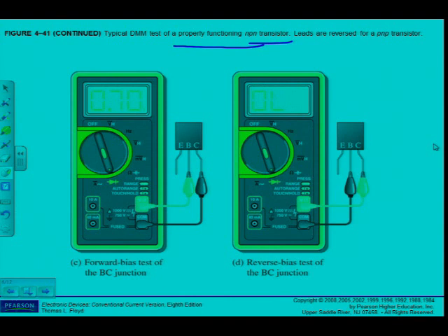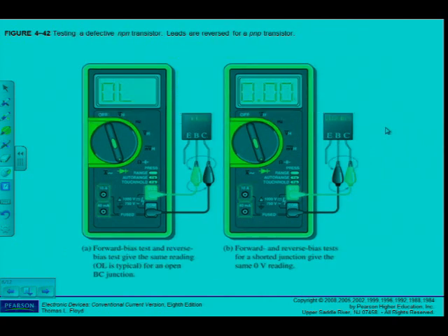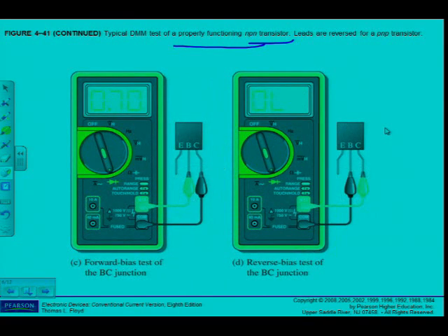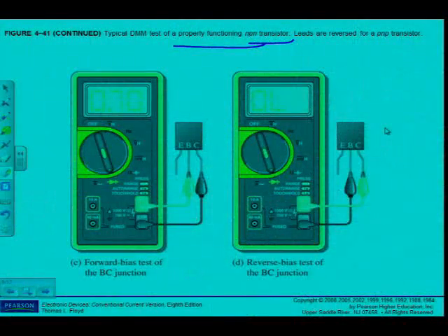All right. If I go and test a transistor using the ohm setting, it's not discussed here. It's discussed in the textbooks, however, at the bottom of the page, just below figure 441. Some multimeters of course don't have a diode testing or an HFE socket, but then you can test the transistor by using the ohm setting.